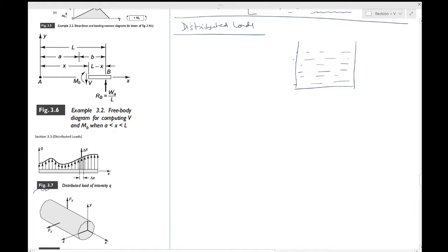Okay, now if the pressure over here is P atmosphere, which is exposed to the atmosphere, and the height of the container is h, for example, the pressure will vary from P atmosphere to this maximum value, and this pressure over here will be P atmosphere plus rho g h.